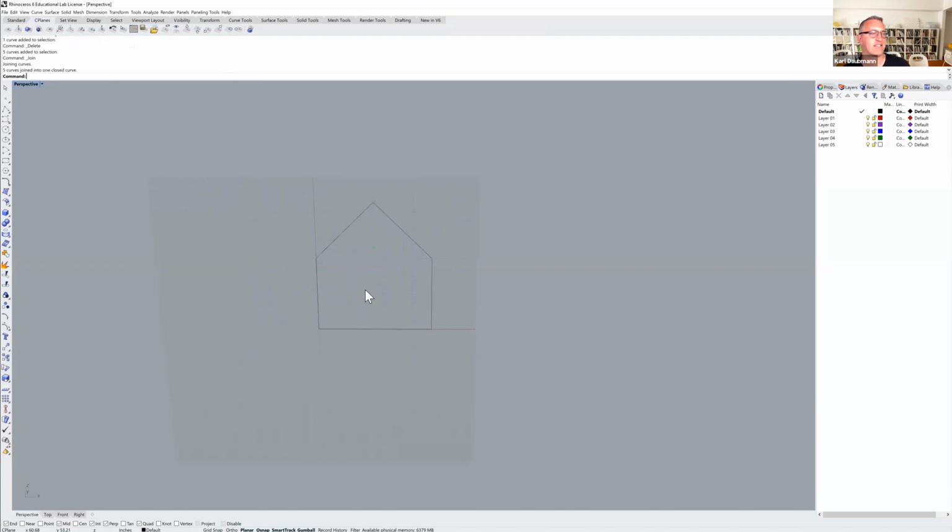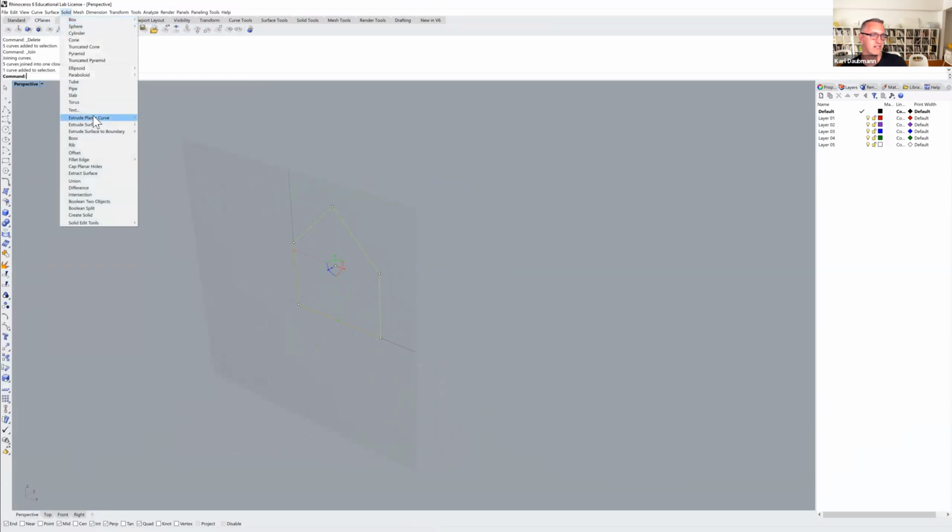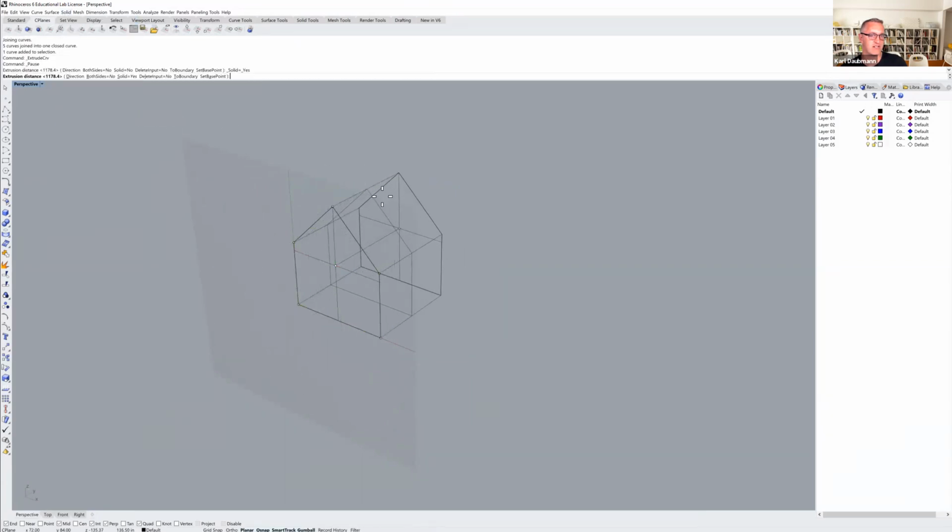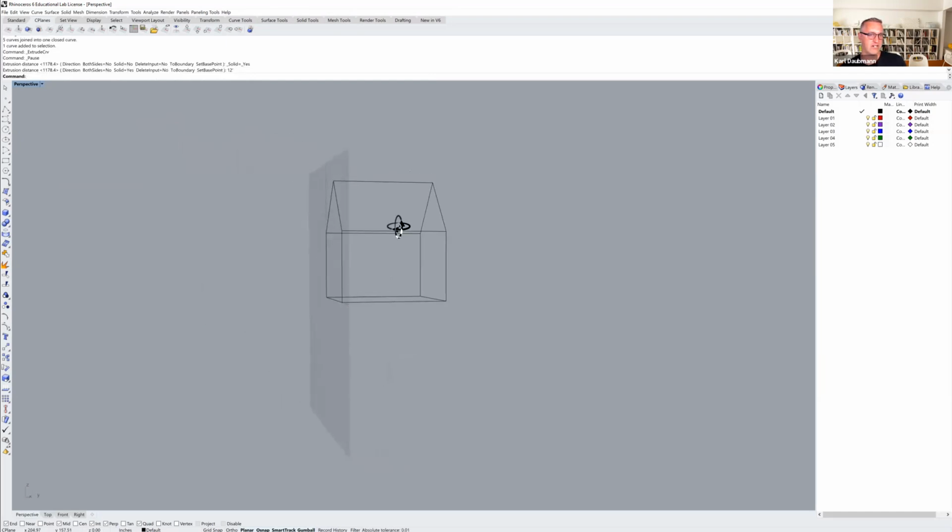I did it really fast, I know, but just in terms of drafting something and how you would work with lines so that you could see, okay, I drew a kind of rectangle first with key dimensions and then drew a few other things. In 3 dimensions, what I would do is extrude this, even as a solid, extrude planar curve straight. And now we have that object.